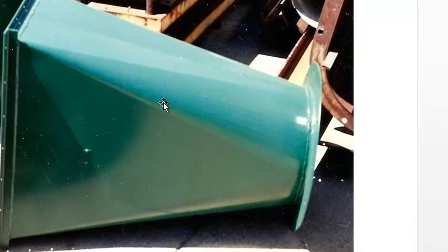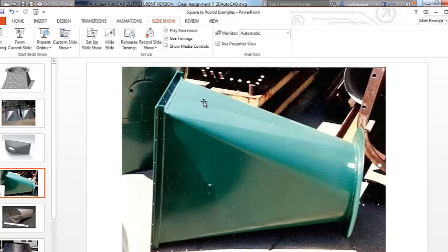Here's another piece of duct that's been step broke, in halves. I don't have a seam here, but I have a seam here, which leads me to believe there's a seam on the back side here. So this one's been formed in two pieces, and I told you we're going to talk about these seams in just a minute. I'm going to show you maybe a little 3D version of what's going on there. But they've actually done all the press brake work and turned this thing in two pieces. So that's probably the smallest parts I can break it down to, but maybe not always the easiest to fabricate.